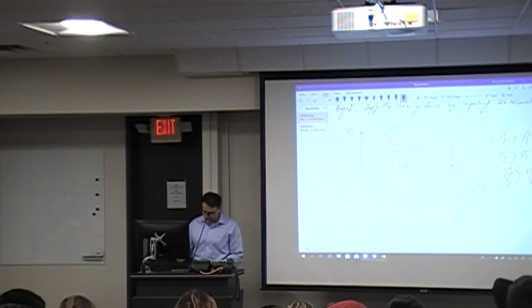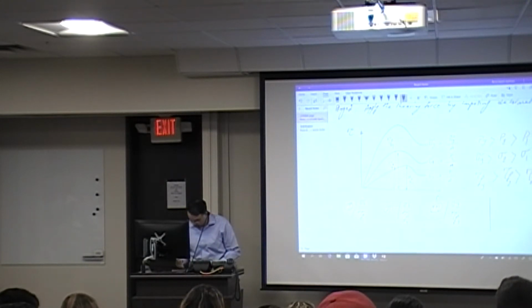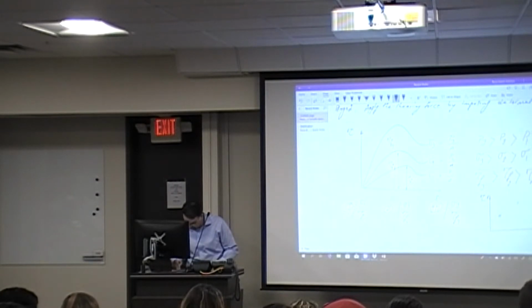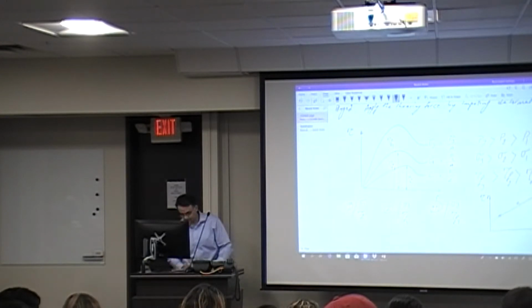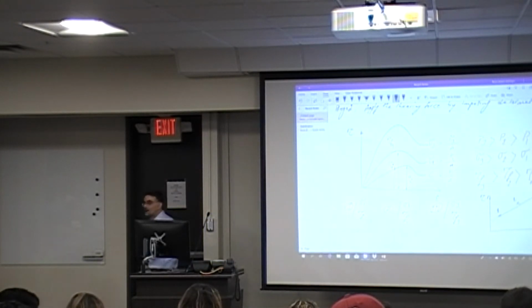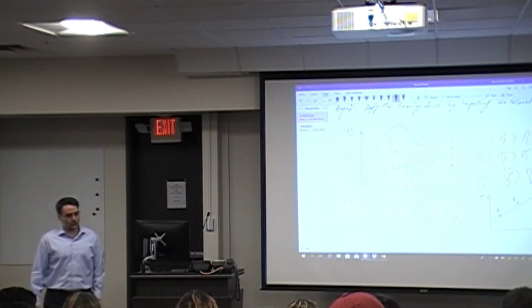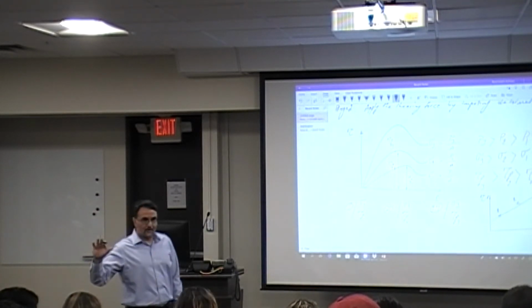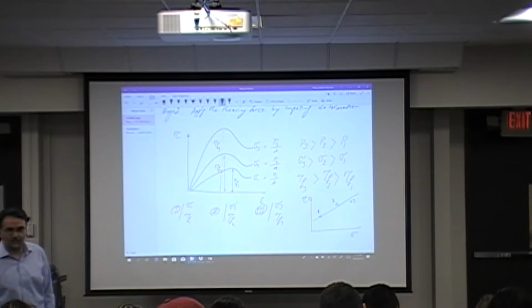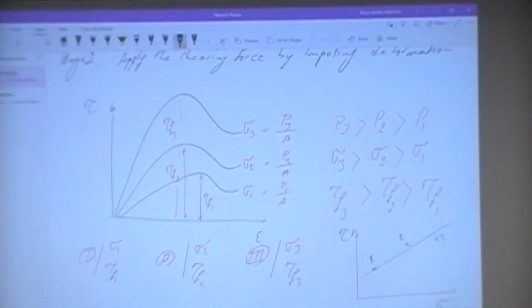Now I have 3 points, which represent the failure. So if I go back in my sigma versus tau plot, this could be point 1, 2, and point 3. Do you agree? So you run the best line that results in the minimum mean square error between those. That's the trend line in your Excel spreadsheet. That's how it works.